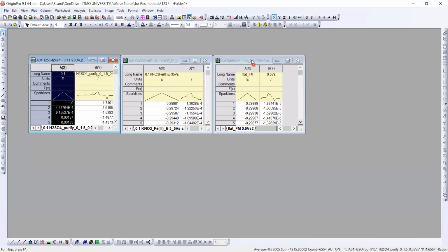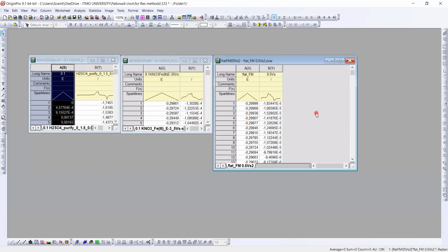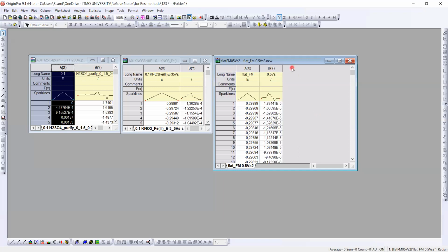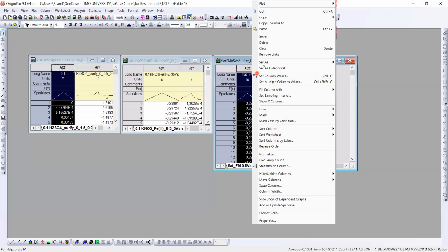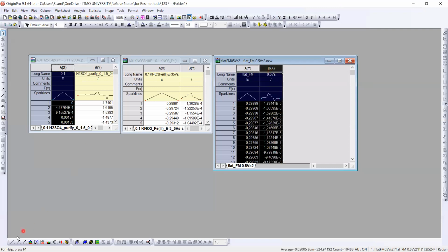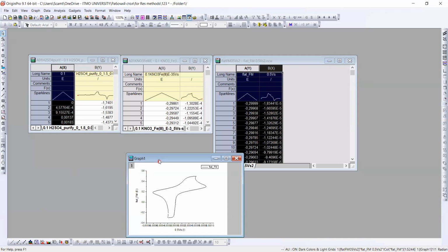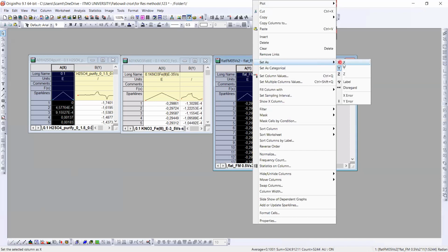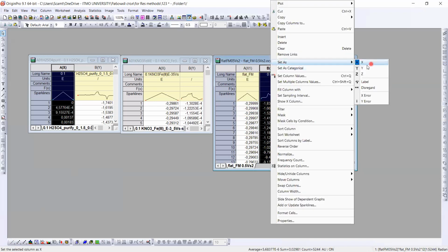Origin Pro can build graphs, but it can build them only from regularly, subsequently ordered columns, because columns should be X, Y, and X, Y, Z. If you set it as Y, for example, and put it as X, and you want to build the graph, it could, but it inverts the graph. And usually, if you have more than two, you will have a problem.